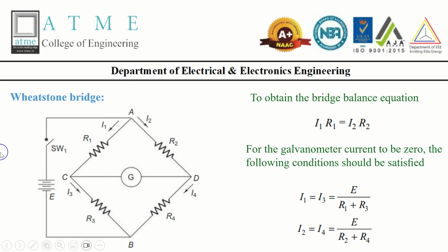Look at this, here we have a diagram. In this diagram, E represents the voltage source. R1, R2, R3 and R4 are known resistances with precise values. Rx is an unknown resistor you want to measure. The voltage across the middle node, where R2 and R3 meet, is measured to determine the value of Rx.